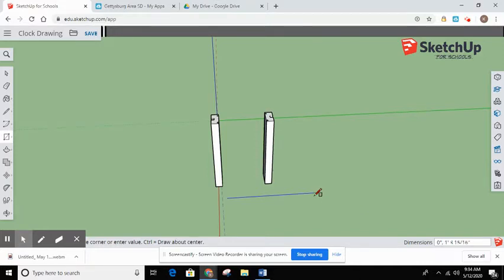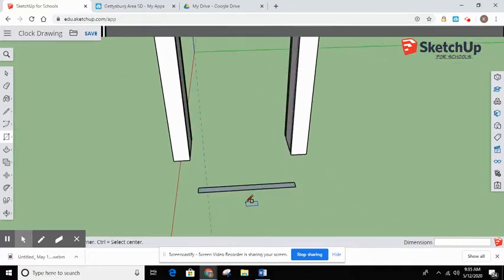Okay, so in this drawing, because I'm on edge, 1/2 inch is going to be one of my measurements here. Looking at my dimensions in the bottom right, that's how I'm determining the direction that I'm going. You can see it's 1 1/4 inches by 1 foot, 4 3/4. So I need to start with my 1/2 inch measurement, comma, and then I'm going to make that the length, which is 6 7/8 inch. And then I'm going to hit enter. And there is the profile of a B.